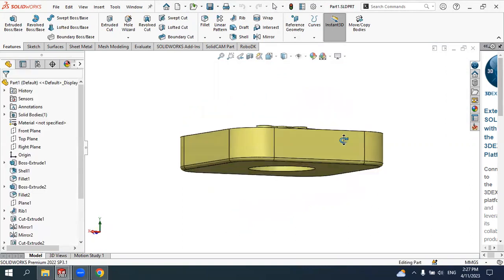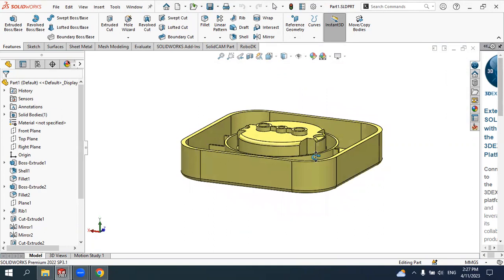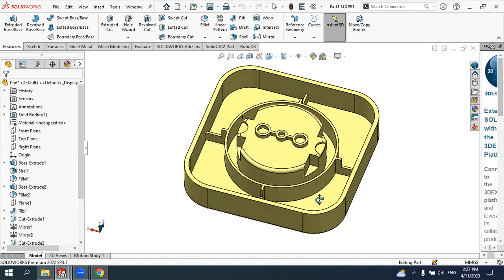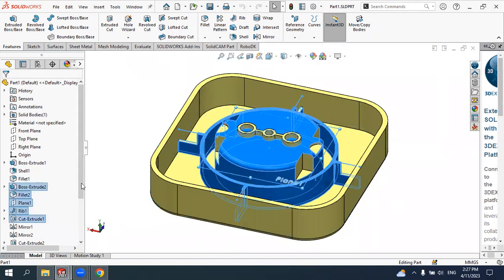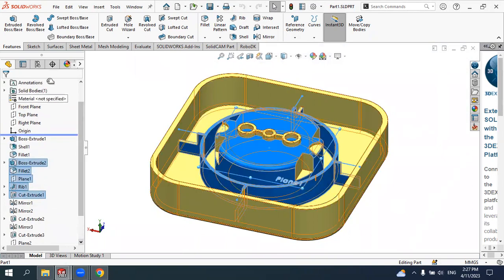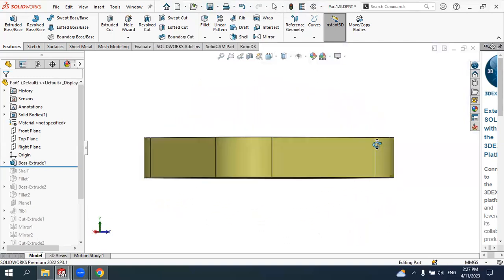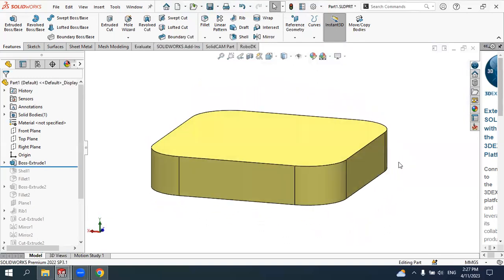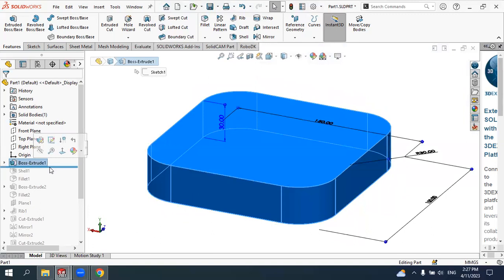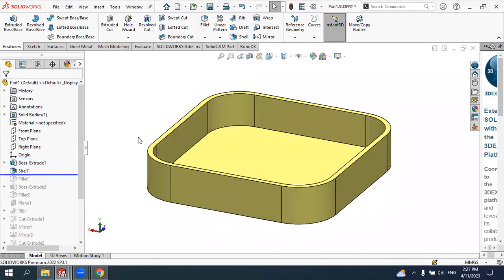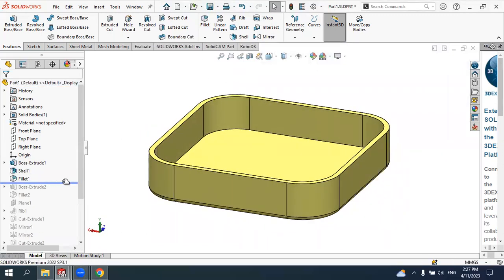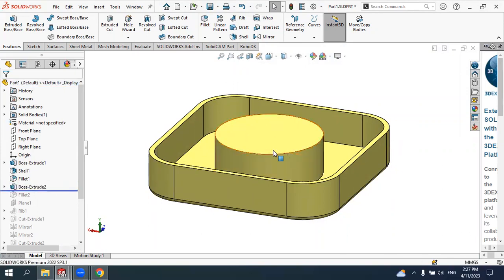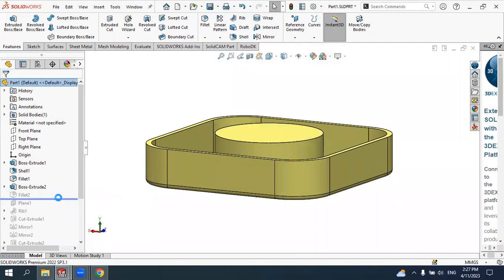Now it's opened. Here you can see some examples of plastic elements designed in Solidworks. Let me go to the initial condition here. Initially, this solid element is extruded using just a single extrude boss function. You see it is too simple. You see the boss extrude is used. And then as a next step, it is converted to a plastic element using the shell element and so on. Other features are created here, again one element here, the fillet and so on.